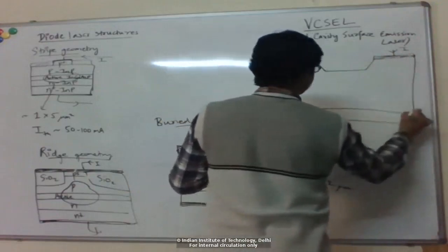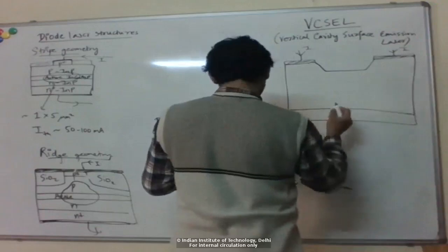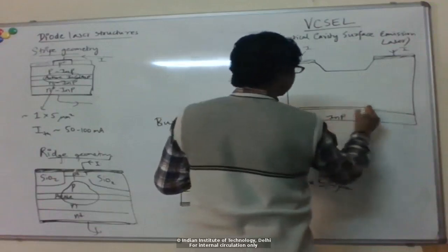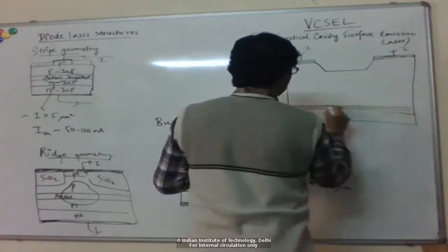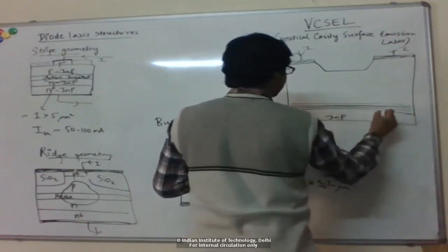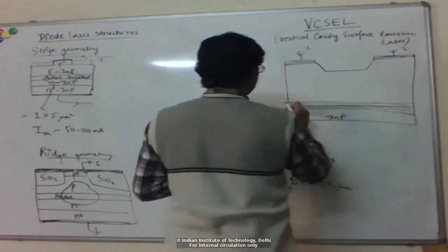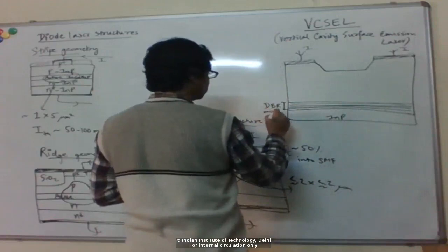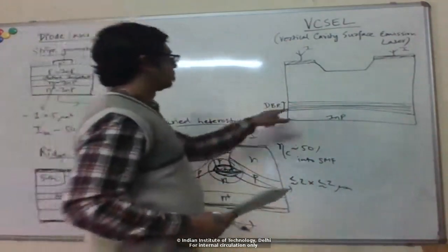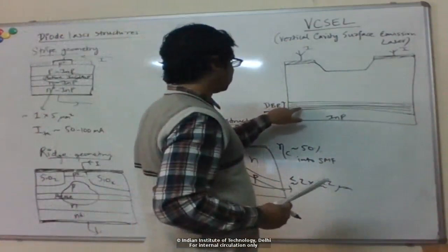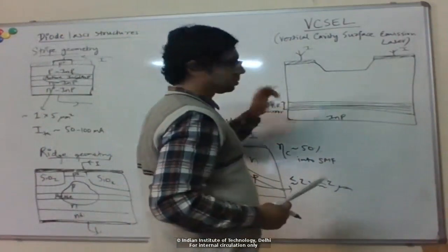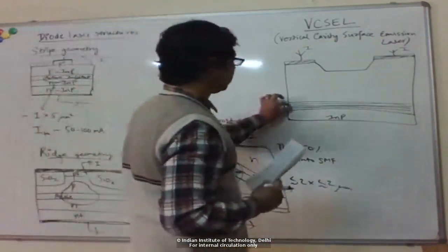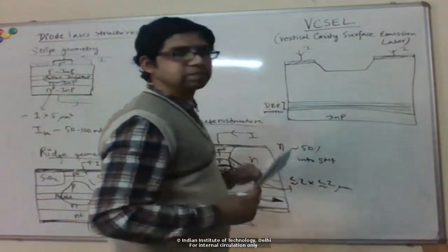Okay, and then what you do is basically, on top of your substrate, which is indium phosphide, right? What you first do is you grow multiple thin layers of alternating materials, right? High index, low index, high index, low index. So you grow multiple layers here, which act as a DBR mirror. So, right, you alternate between some different material compositions here, and you get this Bragg grating of high and low indices. Okay. So typically these layers are very thin, like maybe 10 nanometers, repeating many times, like 10, 20 times.